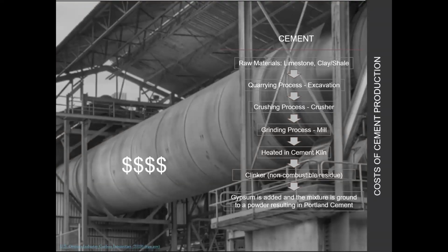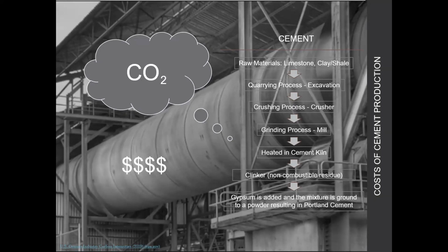There are a lot of percentages out there, X percentage of the industrial sector CO2 emissions attributed to cement manufacturing alone. So that's why when you hear low carbon concrete, what we are probably doing, whoever is involved, is looking at reducing the cement content. Cement is also a very high cost ingredient relative to the other ingredients in concrete. So, if we're reducing the cement in concrete, wouldn't it also make sense that we would be reducing the budget?